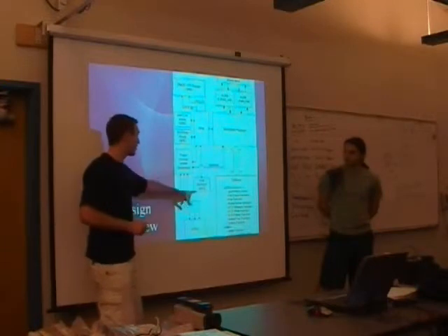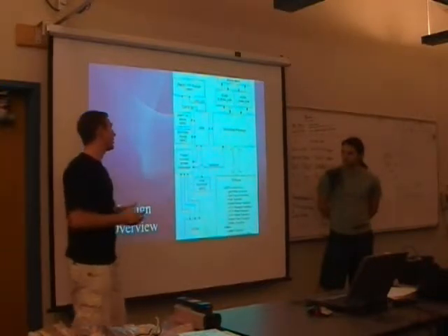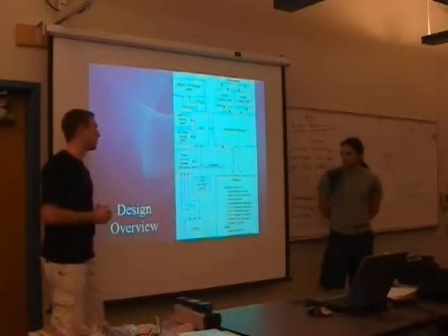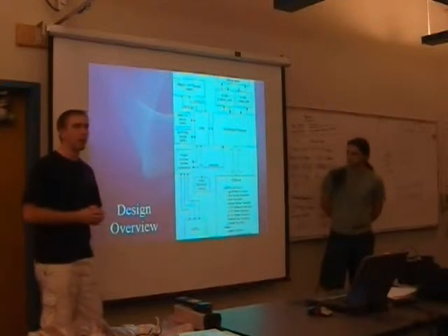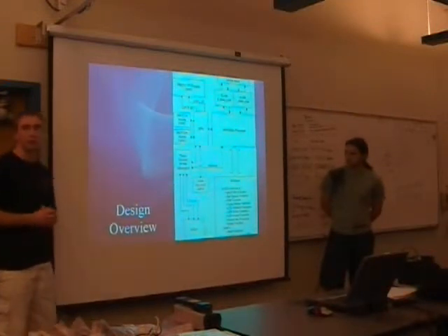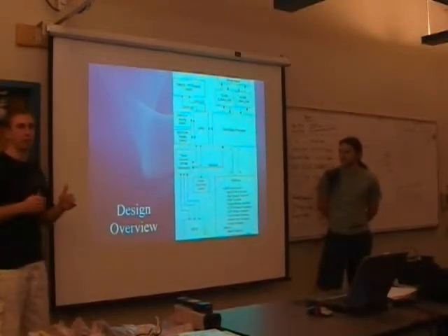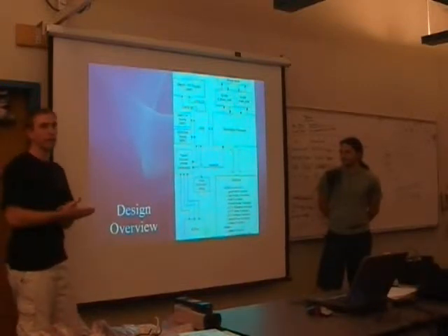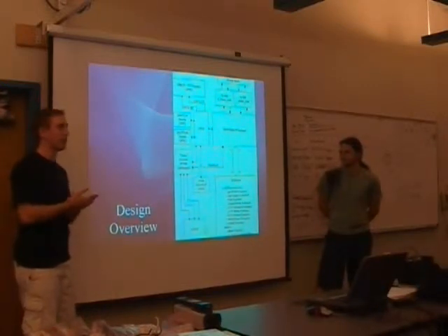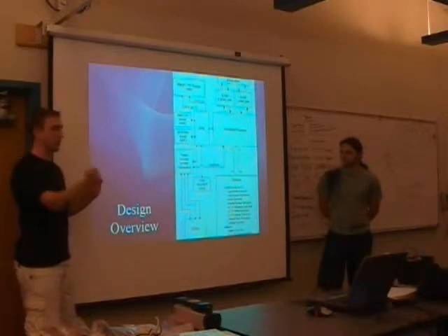We also have an IP core that we created that uses the external VHDL file that they supplied us, and then we modified it a little bit so that it sends all black RGB when it's on the blank portion of the screen, because that's wrap back around.